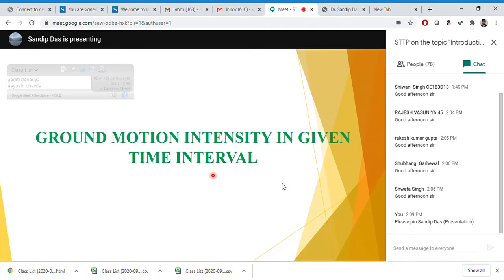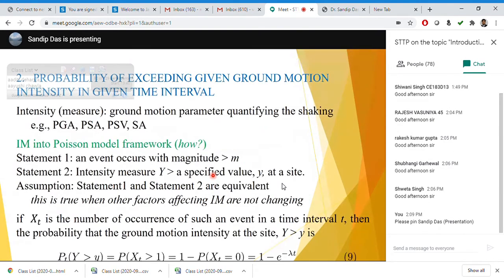If there is an earthquake of magnitude 7 or 8, quite large, but occurring in Japan, it will have no effect on a structure in India. So we are now interested in first estimating or understanding the intensity. Intensity is a very different quantity from the magnitude itself. This is actually the real tremor that you feel at a site.